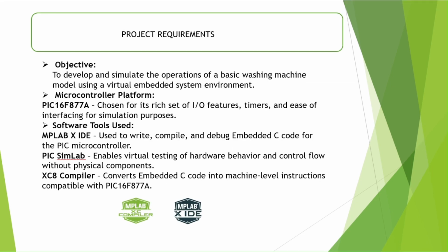Our primary objective is to create a virtual embedded system environment that accurately simulates the operation of a washing machine. This allows us to test and refine our design without the need for physical hardware in the initial stages. For our microcontroller platform, we selected the PIC 16F877A.